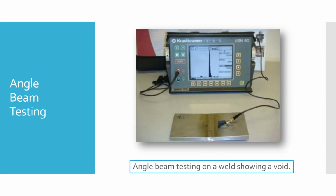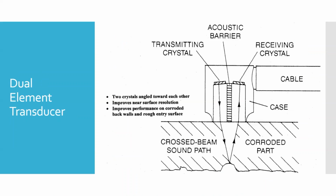And so there's that application I was talking about where we have a piece of welded material. We can't go directly above it. We want to look at the quality of the weld, so our angle beam is coming off from the side. And what we get is a display that shows essentially a depth or a distance turned on its side, okay? So the face of the probe is here. The further away a return signal is, the further to the right it is. And we'll look at that more in a straight beam situation.